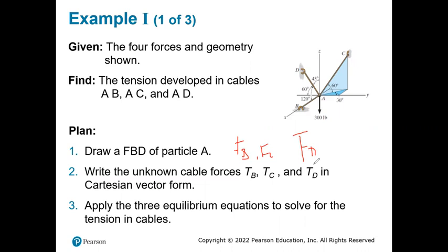So we always may mark it as force, and then after solving, when the sign comes positive, we say that as tension. When the sign comes negative, we say as compression. So in my case, I'm assuming them to be tension. So I say that everything has to be in tension.